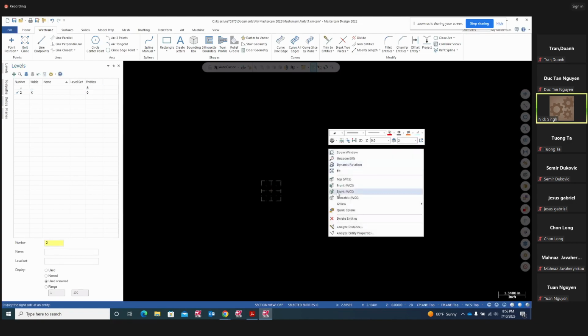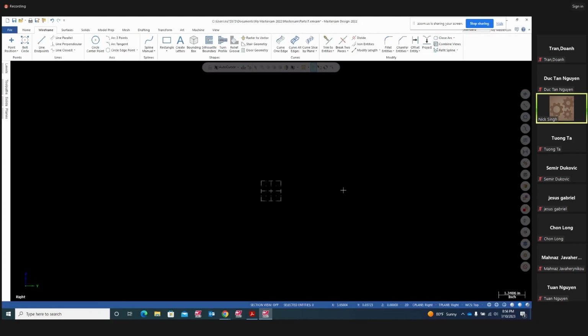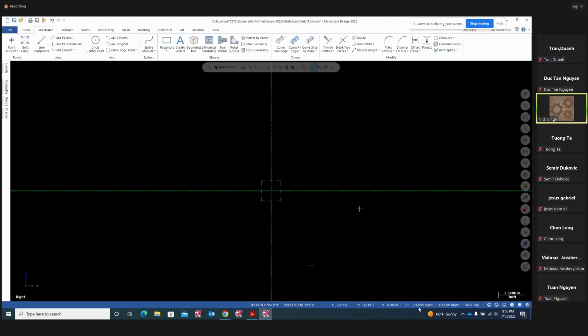And I go to construction plane right. And my function is going to be key. We are in construction plane right. Okay, good. So now construction plane right, I'm going to change my Z to minus 1.5. That's where I'm going to have that big circle, which is diameter 5.5. Okay, let's do it.